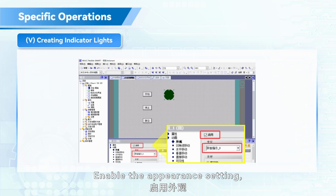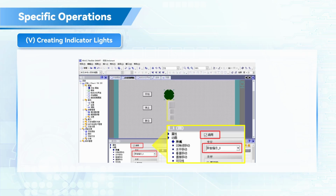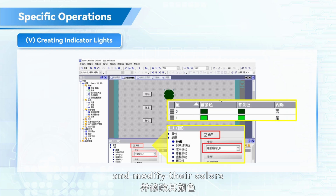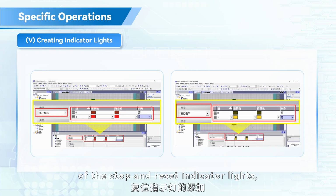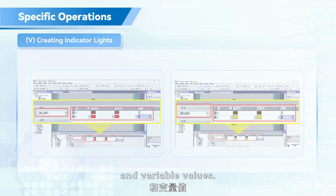Enable the appearance setting, and set the variable to start indicator light 0. Add two new values, 0 and 1, and modify their colors and blink settings accordingly. Similarly, complete the addition of the stop and reset indicator lights, and configure their appearances and variable values.